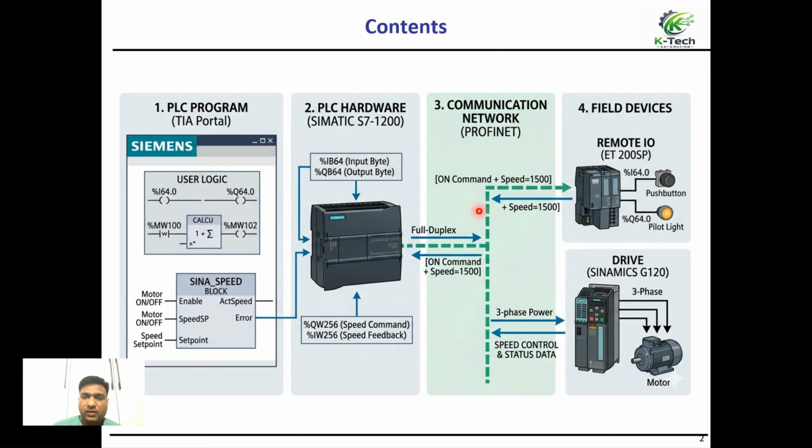Definitely the number of cables and everything will be reduced using Profinet communication, because all the signals will transfer via the communication. The speed will also be high. This is a big advantage if you require a high speed system, so use the network communication of the remote IOs.